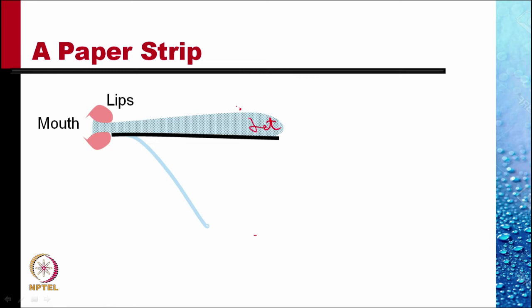paper rises. Pressure is less, but less than what? We have to follow a streamline, and the streamline of air would come from within the mouth. The pressure there is not atmospheric, the pressure there is more than atmospheric. So there is nothing that shows the pressure at 2 should be less than atmospheric. So that will create a lift on the paper. So clearly, Bernoulli equation is the wrong explanation for this phenomenon.